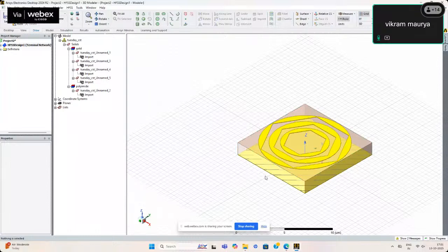So in the x and y, we have to choose the same thickness and width and height. It must be there, the L and W. And in the z max direction, we have to make a boundary like the box shape structure, in which we have to create a free space or vacuum. So that one can easily make a boundary box here.